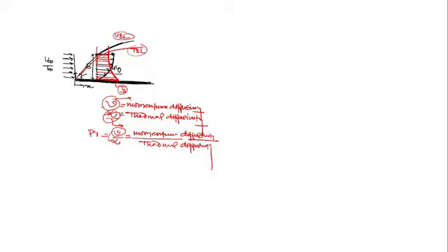Yes, in terms of thickness of the boundary layer, if momentum diffuses faster than heat, then obviously the variation of velocity in the y direction is found to be more than the temperature variation. Then the thickness of the velocity boundary layer is more than, if I'm saying this as delta, and delta th is thermal. So can you say this Prandtl number, which is nu upon alpha, can be approximated as,